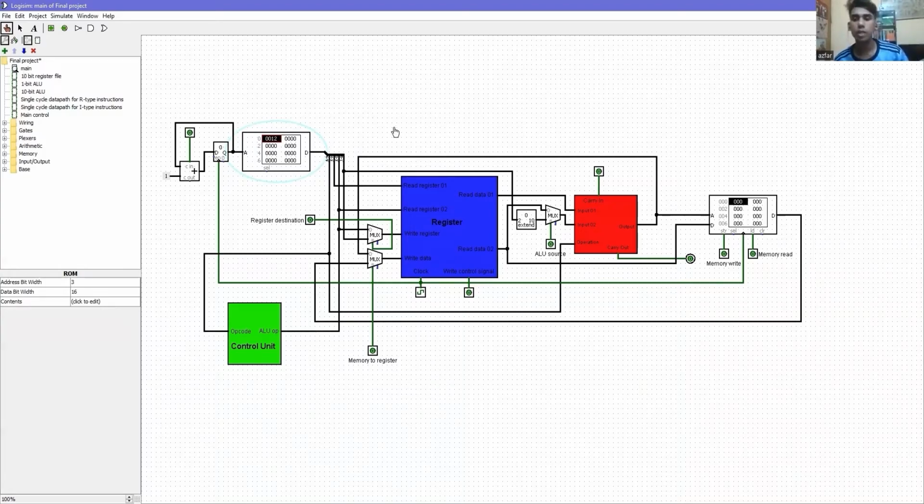So we know that I'm going to do the AND operation, and for that we're going to take the opcode as 0. So we have made it 0, and the second one is for RS, the third one is for RT, and the final one is obviously for RD. So we are going to take 2 registers, do an AND operation of their values, and store the result in the other register.